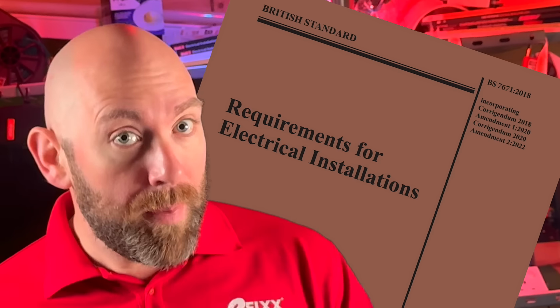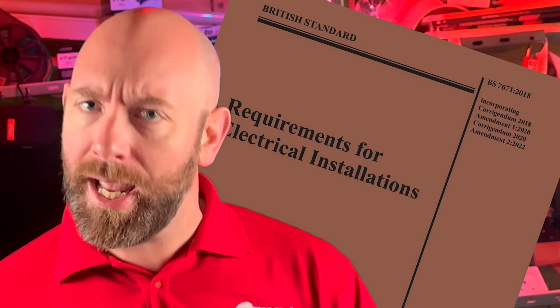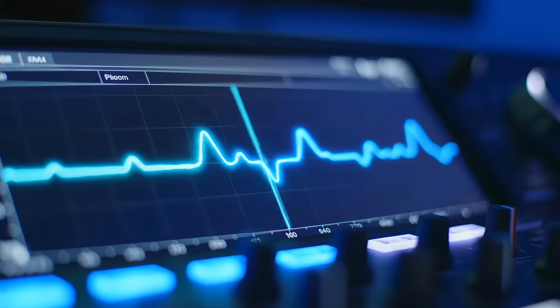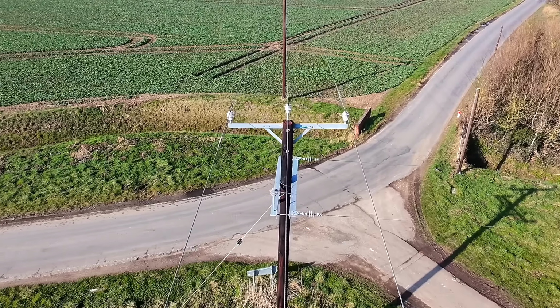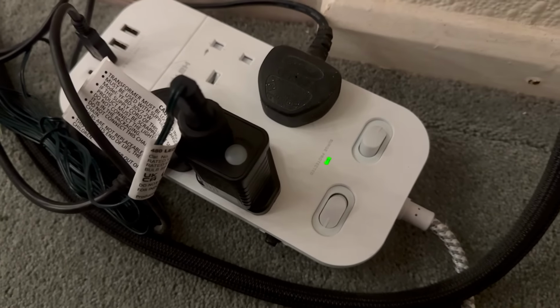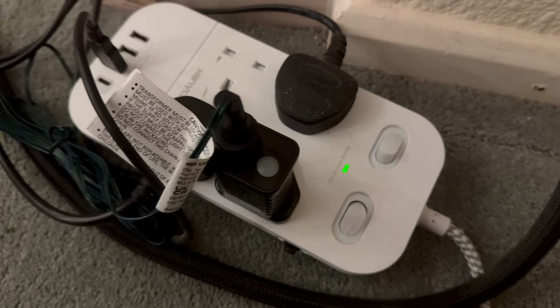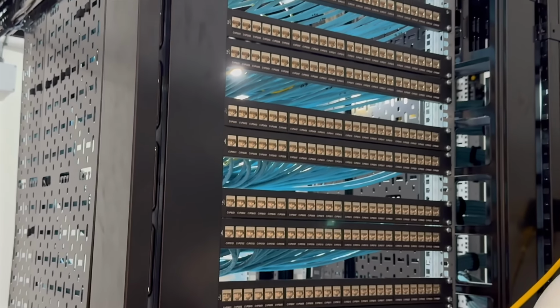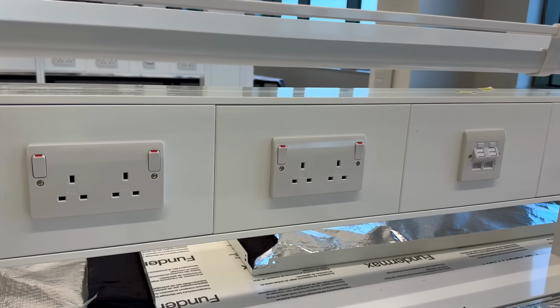So let's remind ourselves what an SPD is and why it actually matters. Section 443 of BS 7671 deals with the protection against transient overvoltages. These are short duration spikes in voltage caused by switching events within the installation or atmospheric influences affecting the supply network. They are not overloads and they are not sustained fault currents. Modern installations contain a lot of electronic equipment. Control gear, drives, LED lighting and IT systems all rely on components that are sensitive to voltage spikes.